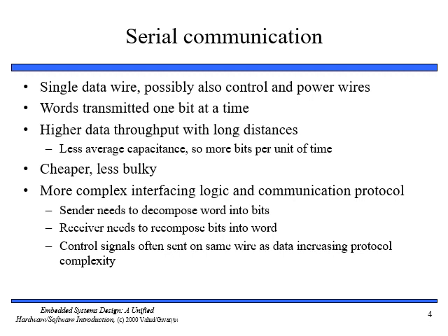Serial buses are capable of higher throughputs than parallel buses when used to connect two physically distant devices. The reason for this is that a serial bus will have less average capacitance, enabling it to send more bits per unit time. In addition, a serial bus cable is cheaper to build because it has fewer wires.